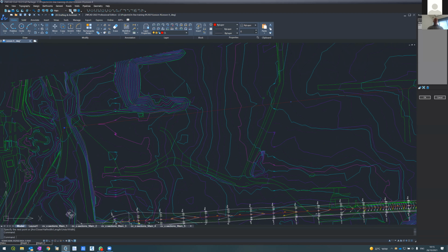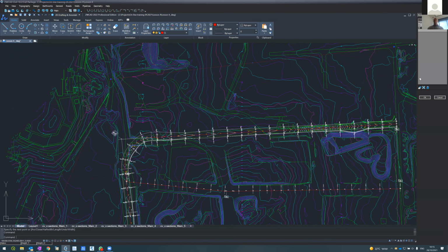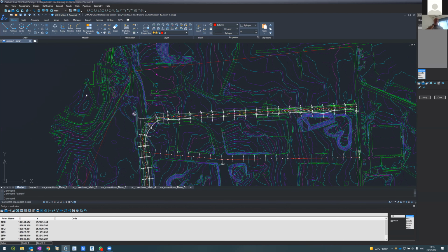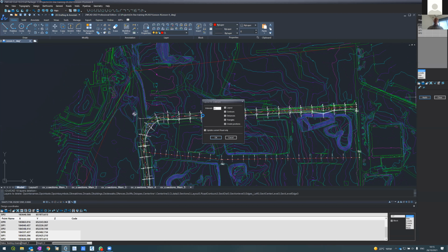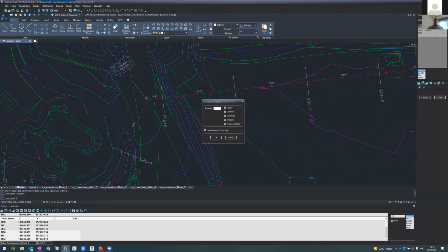And on this road, go to horizontal alignment, go to the highway, select the polyline, enter again, apply, and I will get 1, 2, and 3 IPs, right? This is exactly the same as what we did in our last session. Now, here I'll create a curve of 400 meters. Okay, this is a curve of 400 meters.